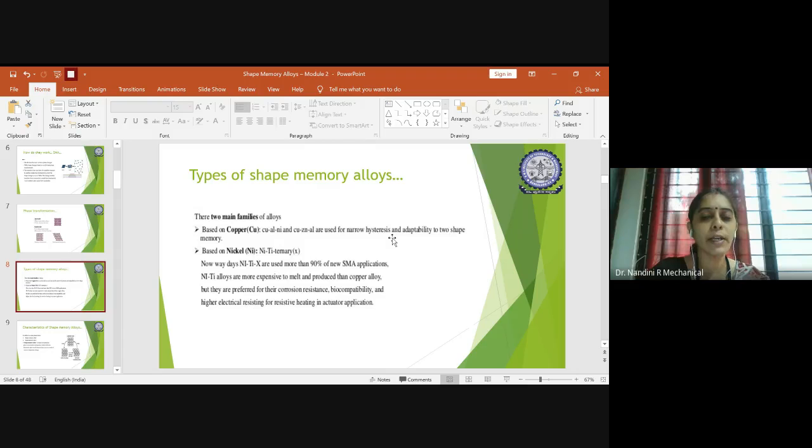Hysteresis loop we had studied already at the time of understanding the ferroelectric nature of piezoelectric materials. So there we subjected the electrical field to see how the voltage is enhancing. Even after the removal of the electrical field, there was some spontaneous polarization, what we called, and then it stored some amount of polarization in it. We call that a remnant polarization. And again, when the total electric field was zero, then it came to the coercive field.